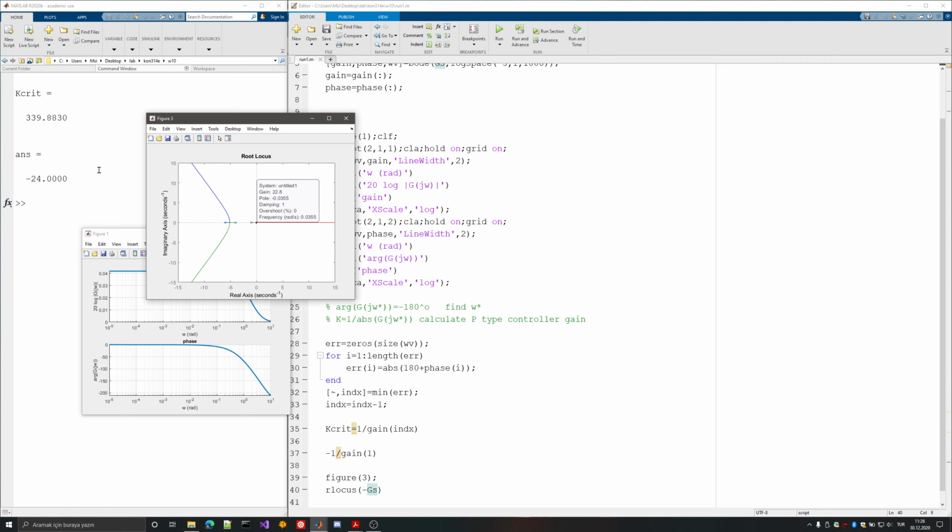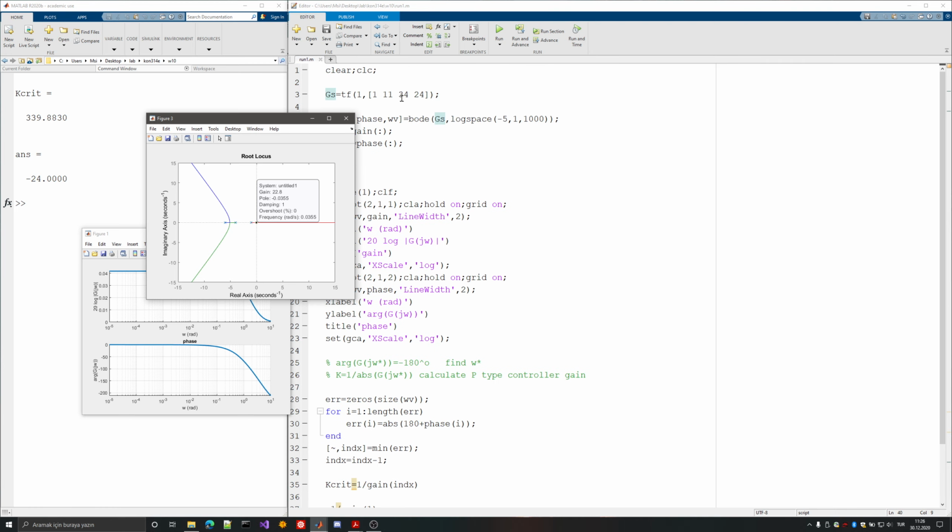Is there a way to calculate this using the transfer function itself? Of course, you can plug in omega and you can look for the solutions where you have the angle condition satisfied, and using those solutions and eliminating the unnecessary ones or the ones that we're not interested in should give you the omega value, and you should then get the gain value and take the inverse and acquire this interval.